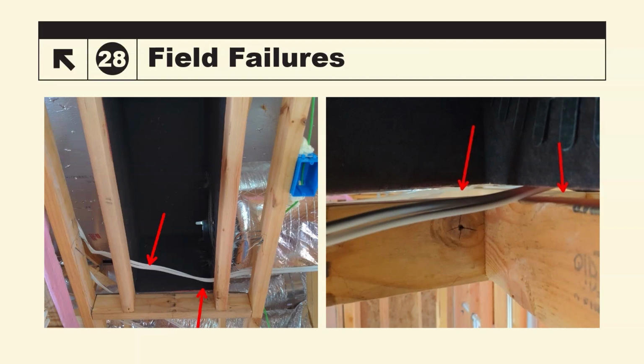It should actually have the wire rerun, or at least, in my opinion, if you wanted to try to fix this the way it looks, you cut a little notch in that and you set all of that plenum, or the return box, down on that framing member and then you seal it. You don't just try to seal up a 1/2-inch gap with mastic, because we know for a fact that that will not work. It's going to dry and crack and leak, and it's going to be more of a problem to try to work around.